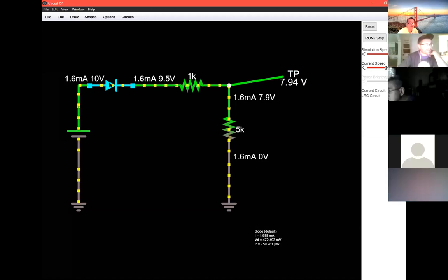I use this file stat for assignment number 5. And if you lay it out exactly how it is on the Excel spreadsheet, it actually gives you an error for the wiring. You need to have all the circuit legs with an individual ground, not one path back to ground. There are some quirks, definitely.